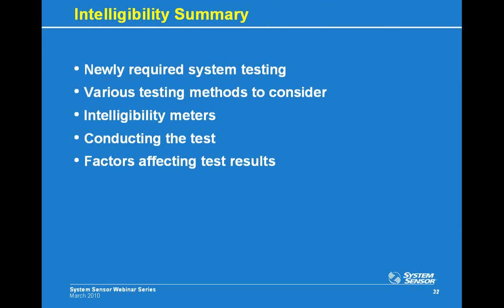So in summary, intelligibility is a new concept that has been added to both NFPA 72 and the UFC document for the military. It is important to take the time needed to learn about intelligibility and understand the different testing methods. If you are involved in voice evacuation or plan to become involved, it would be a good idea to look into purchasing an intelligibility meter, as it is required by the military and suggested by NFPA.